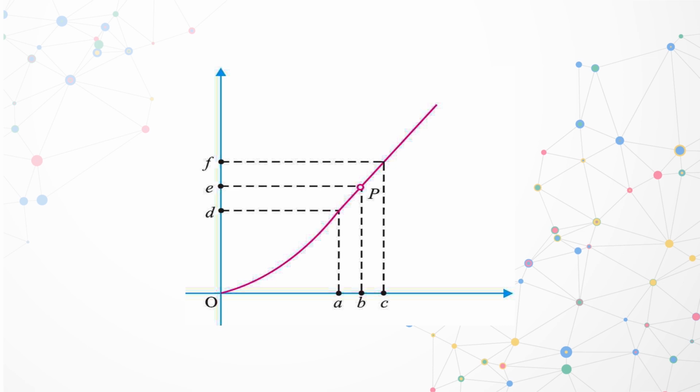So, let us study in detail about this DC forward resistance and AC forward resistance, and let us see how this can be calculated from the VI characteristic. DC forward resistance is also called static resistance. Now, why is this called static resistance?